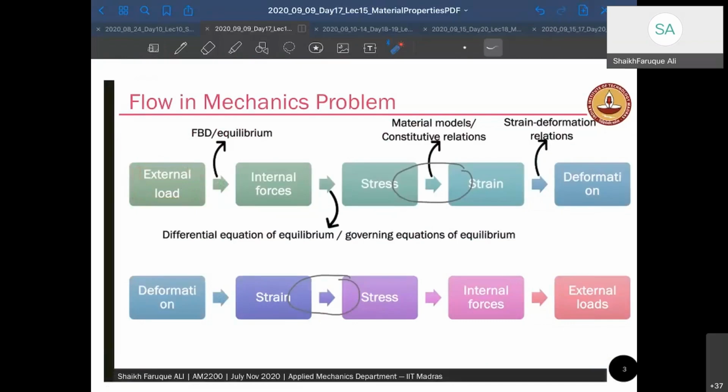Now these external loads are converted to internal loads to understand the mechanism of how the load transfers from one point to another point in the structure itself. So if you have a beam, you know these internal forces are BMD and SFD, right? And if you have an axial member, you have to draw an axial force diagram. So you have to draw the internal force diagram.